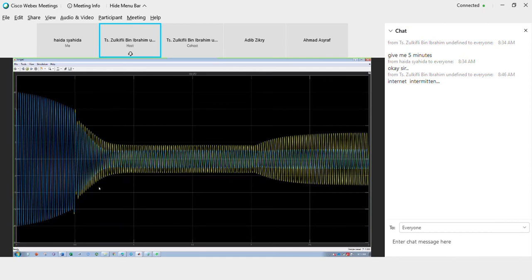Of course you need a very high amount of current to move the rotor because of the rotor inertia. Then the machine starts to stabilize at no load values, and when the machine is loaded at this point, you will see the current increases because you need to overcome that load.